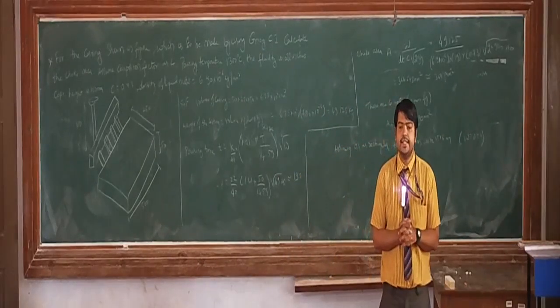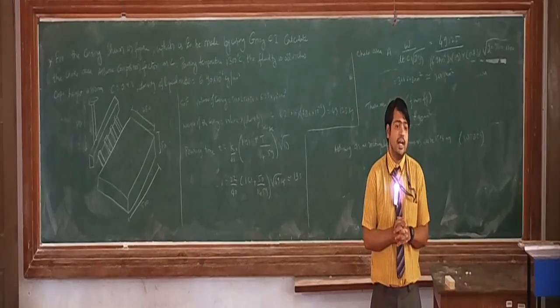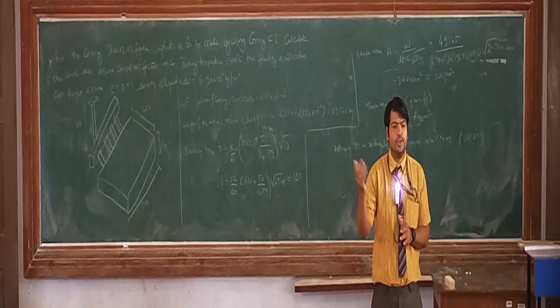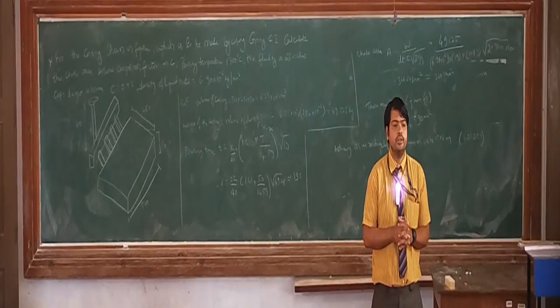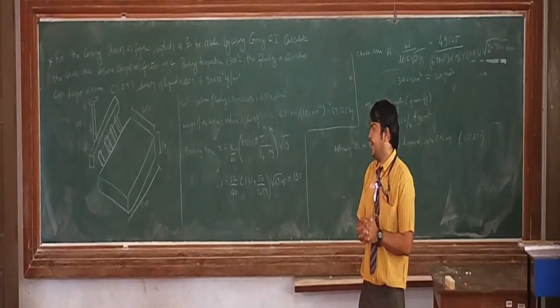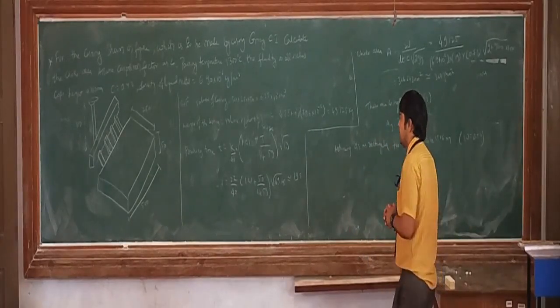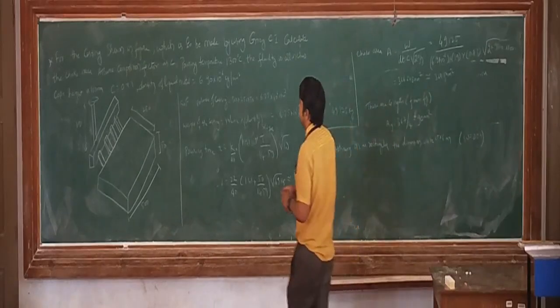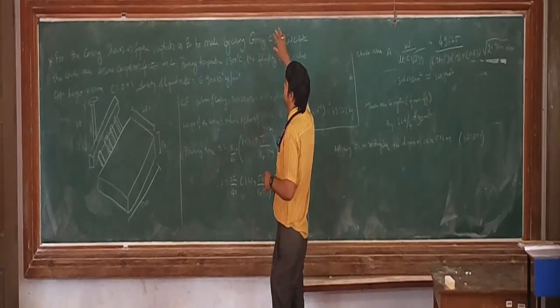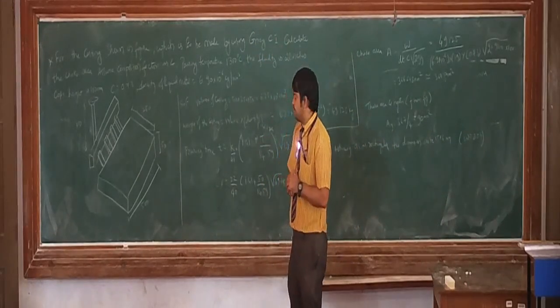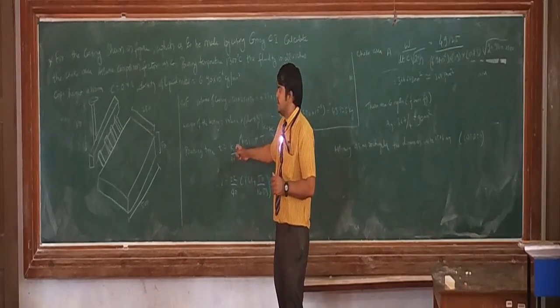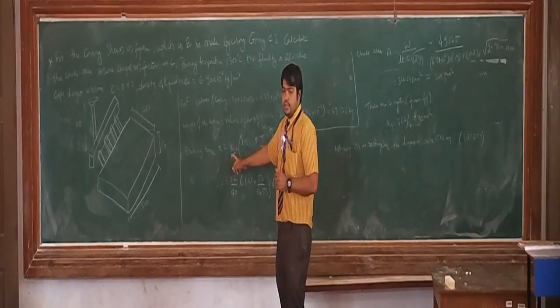So design in the sense we are going to find the dimensions and the geometry. Design is not the drawing. Design is where we find out the dimensions as well as geometry. Here in the question they have mentioned that the metal is grey cast iron. This part of the statement is used for calculating the pouring time, so this will make us certain about what type of formula needs to be used.